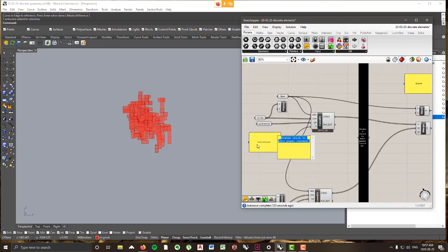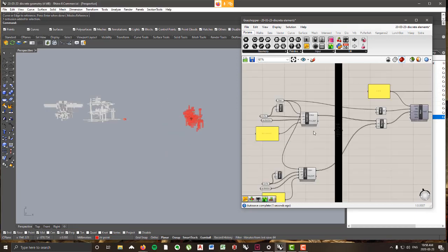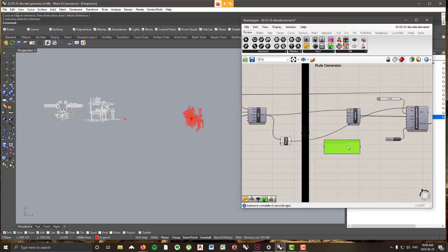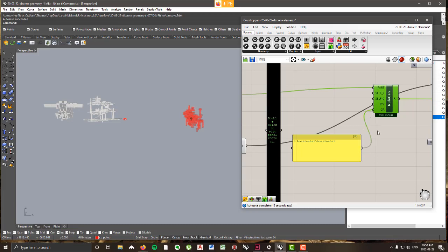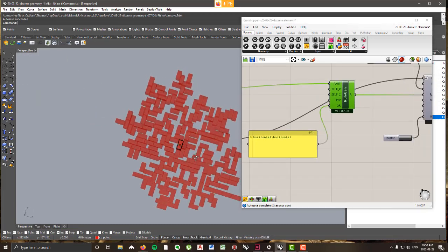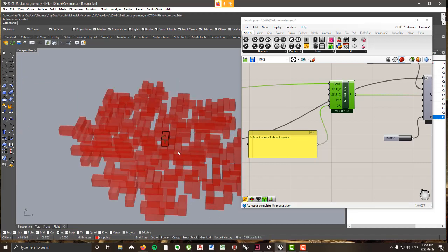And I'm going to refer back to my rules, and we're going to use a syntax like this. We're going to say horizontal greater than horizontal. So horizontal to horizontal, and then I'll click out of that panel. So this is our first rule. This is the syntax that WASP takes. So it's connection name greater than connection name. Now when we plug this into GR and hit reset, it just goes back to having horizontal connections, right? Because we've said that the one type of connection you can make is horizontal to horizontal.